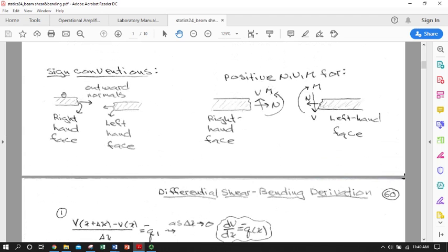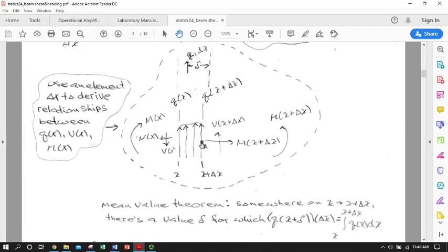We're imagining that we've got a little slice of beam, cut on the right hand side and also on the left, so we have a freestanding little delta x width element of beam. We define point A as a point on that cut right hand side. When we take our sum of the moments and put this little volume element of beam in static equilibrium, we're going to take our moments about that point.